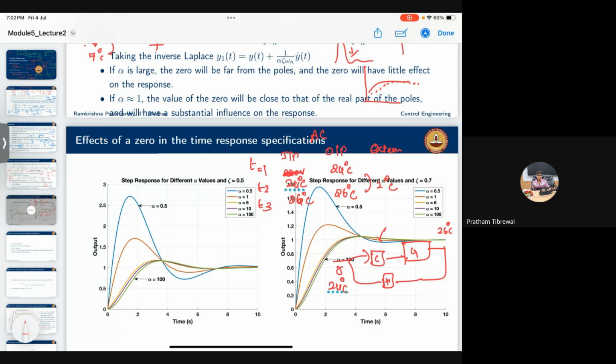So if you have only a proportional controller in your system, if you designed only KP, no KI, no KD, this KP will be changed so that the output will become 24 degrees Celsius. The value you set as KP multiplied with this actual plant will give you 24. It's the difference between the actual and your output sensor feedback, so the error. So here we can see how the feedback is working and changes the value of KP.